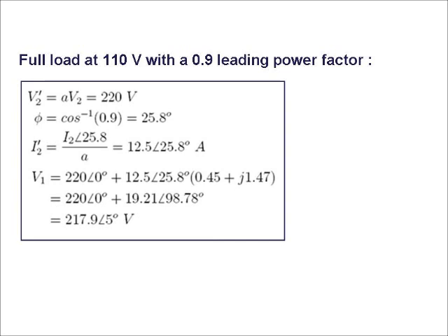If you have 60 hertz, your period is 16.66 milliseconds. So that means 2 pi or 360 degrees. So you just make a proportion and you can easily sketch a voltage and current waveform. Okay, so that was a deviation, but just to emphasize a few important things. Coming back to this slide here.